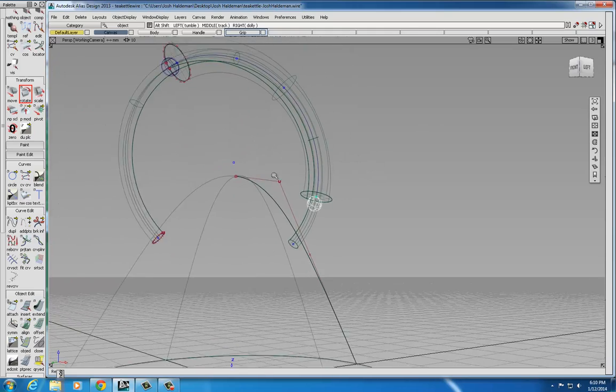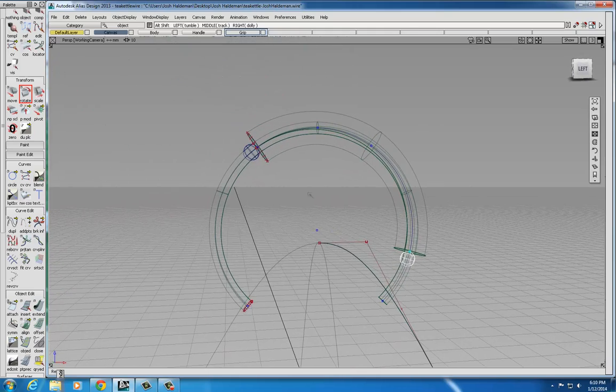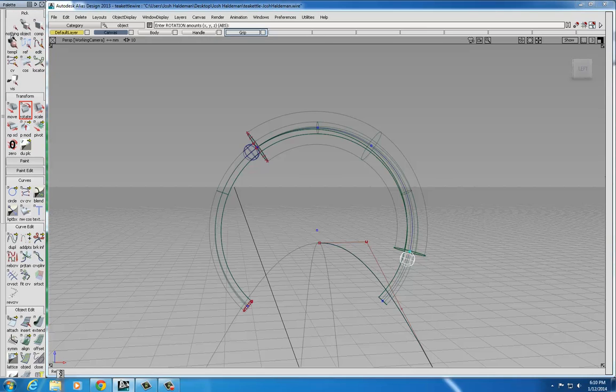All right. So that's it for the grip decoration. We've got those parts on there now. If you want to go in and you want to add the toruses that rest behind that, you can do that as well. You can use the same procedures for that, but it's the same procedure, so I'm not going to cover it again. You could put these grip decorations on the grip layer if you prefer. That's fine. I'm going to pick them both by choosing Pick Nothing, Pick Object, selecting them both, going to the grip layer, and then assigning those objects. All right. Make sure you save your file. And then we'll go on to the next step.